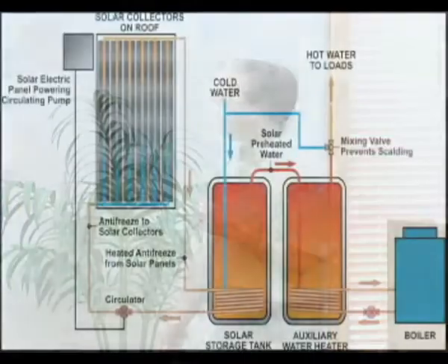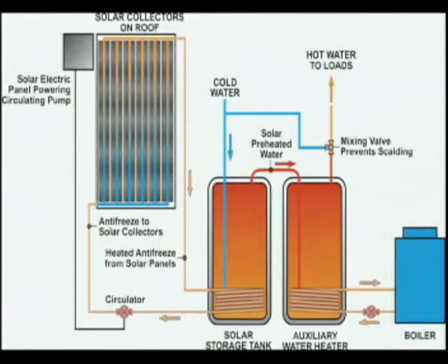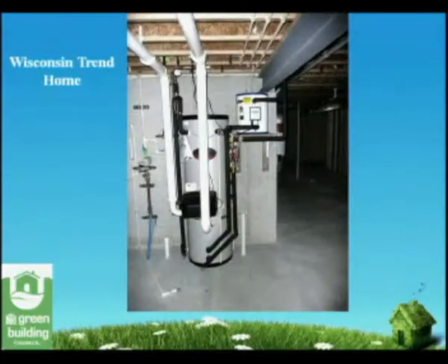So you'll see traditionally 2 tanks in your basement for the solar hot water. We have our collectors on the roof. We have our heat transfer fluid that goes up, takes the energy that's collecting from the sun, brings it back down and circulates through the water in the tempered tank, bringing that water up to a temperature that's much greater, again, than it would be coming in from the street. And then we dump that over into our traditional water heating system.